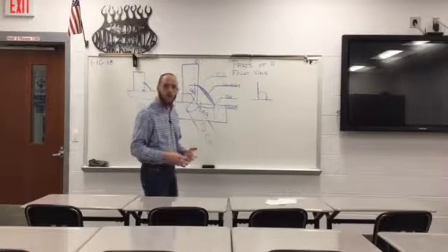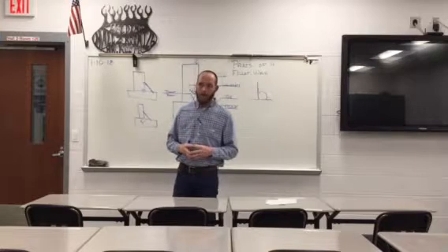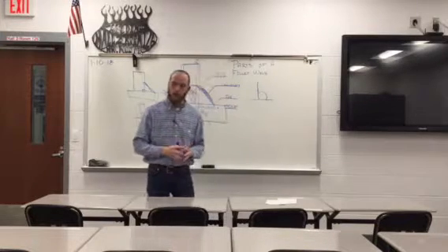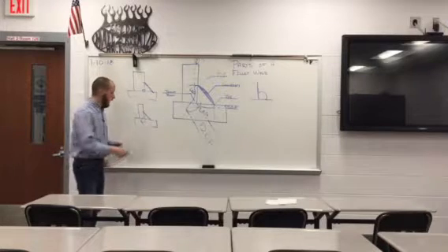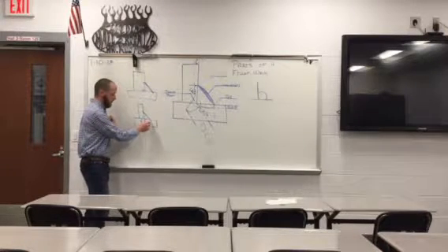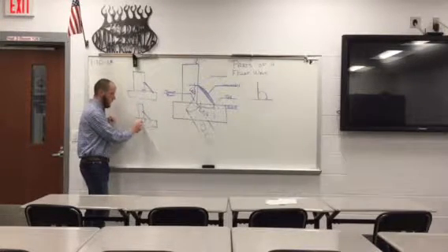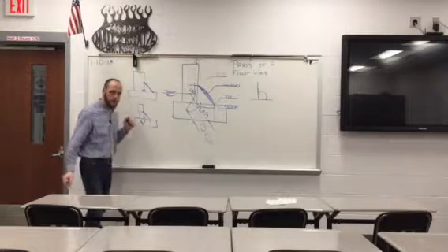That's effectively what has to be there for that size calculation, a strength calculation, to hold. If it calls for 1/2 inch of weld material, not only is it measured out from joint root to toe both ways, it's also measured as the effective throat thickness.